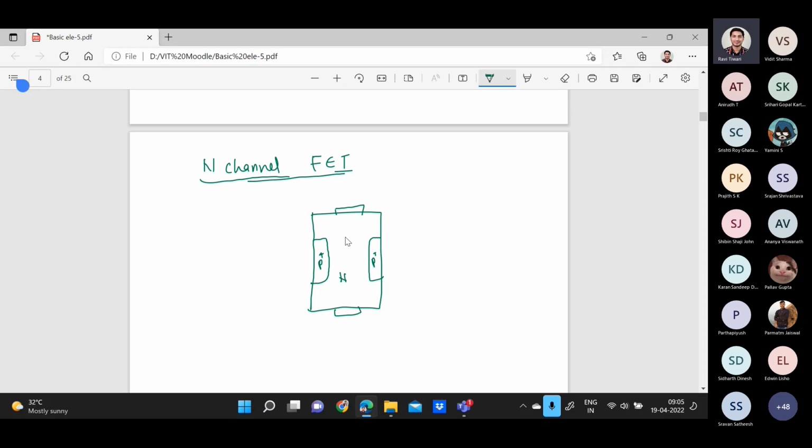and their manufacturing is different. Emitter was highly doped and the collector is moderately doped. Collector is of large size, emitter is of moderate size. But here, source and drain are the same. So you can interchange the position of your source and drain.